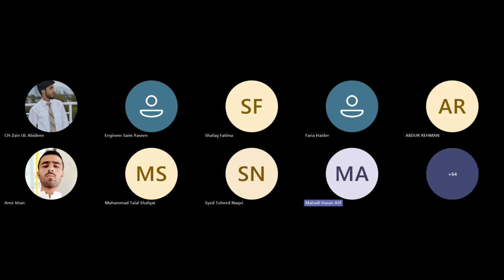Like, for example, what is a HAL? HAL is called hardware abstraction layer. So many times, we don't directly interact with the hardware itself. We have a built-in layer called hardware abstraction layer. So we call the HAL and we interact with the HAL itself. So for you, I would suggest that understanding these layers, which are below the application layer, would be really helpful, and you can directly start working on embedded systems.